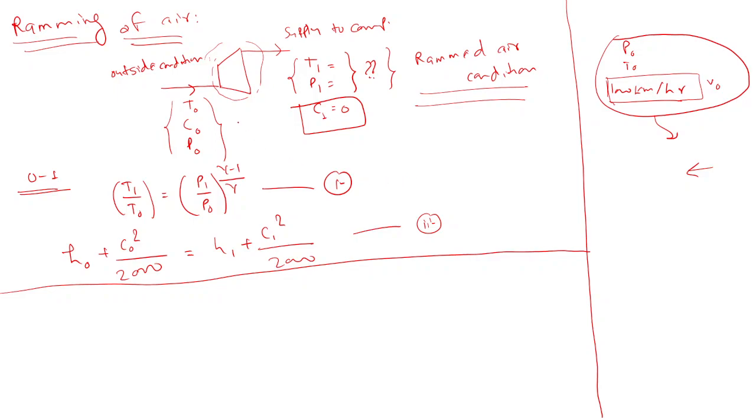Generally it is said that this is some sort of diffuser type of thing, right? Yes, sir. So we can say it is a diffuser because in a diffuser velocity decreases only, right? Yes, sir. Pressure increases. So we can say it is a diffuser. But in some problems they will say a diffuser we have installed there. So here velocity we have reduced. In order to increase velocity we use a nozzle, and here we will use a diffuser.